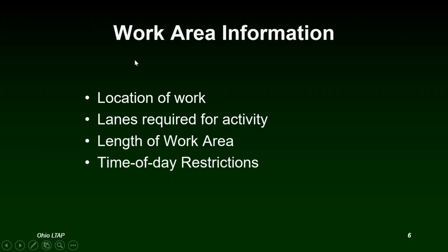during the work week. And if you're looking at maintenance of traffic notes on projects, a lot of times that'll be called out in the maintenance of traffic notes as a restriction from working during those hours. No lane closures during those hours, because we need those lanes to be open during the peak hours.